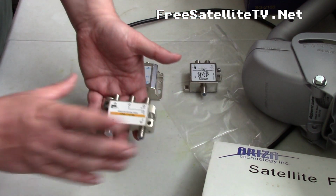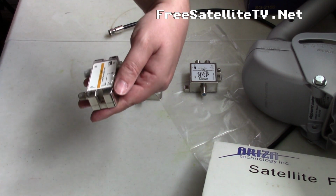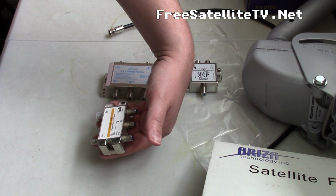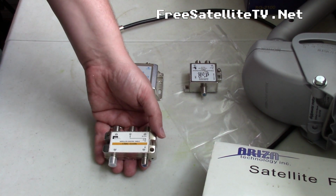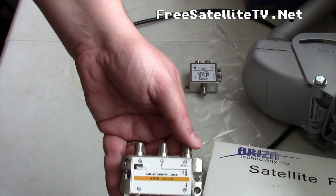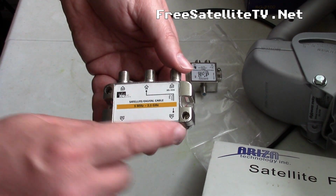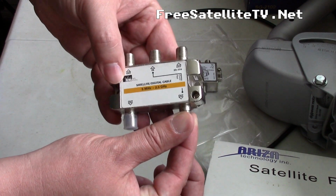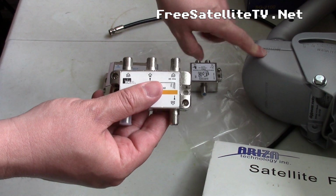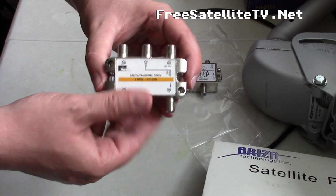Now you got this thing here too, which looks like a splitter, and actually this is a splitter. It's not a switch. This is a satellite or digital cable, 5 megahertz to 2.3 gigahertz splitter, but it has a little trick to it. This line here just indicates the power pass. The receiver that's connected to this one will control the vertical, the horizontal, and also control a motor if you're running multiple dishes. So if you want one receiver to control your motor, you can do it that way.